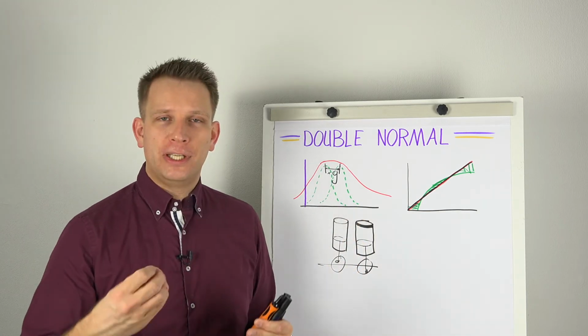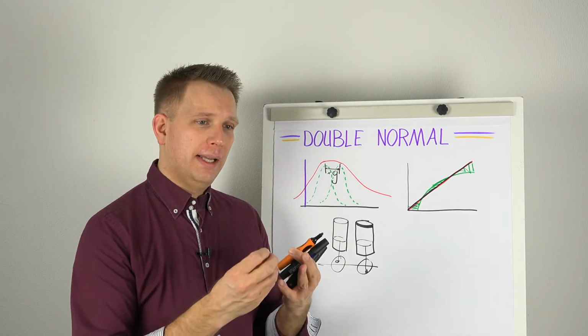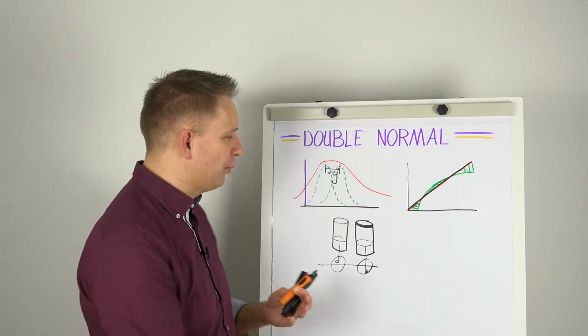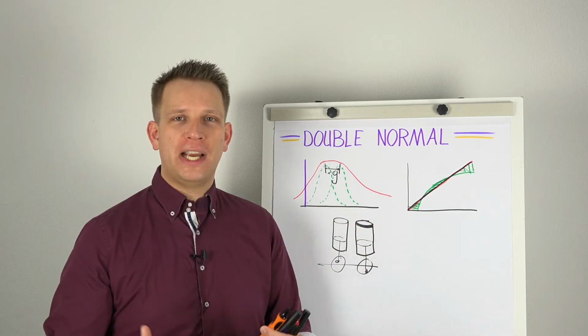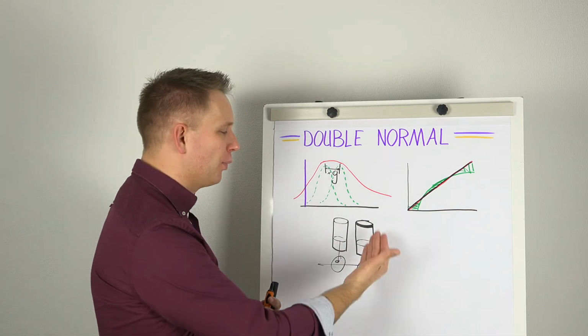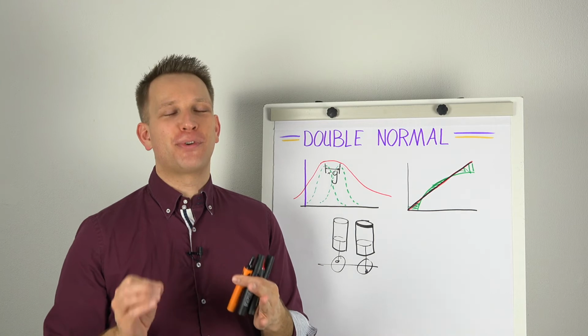Are the valves still working? Are any vacuum or pressure air hoses blocked, or is there perhaps a spring that is not good anymore? So all those things with reaction times, all the usual suspects in bad movement. Is it maybe not lubricated enough, things like that.